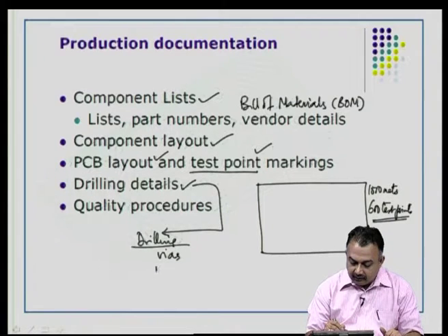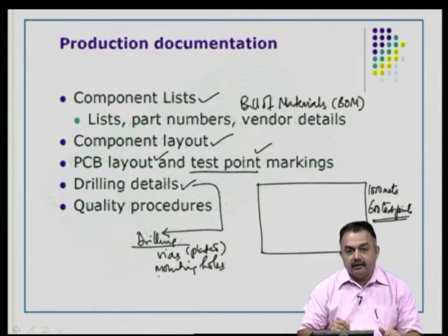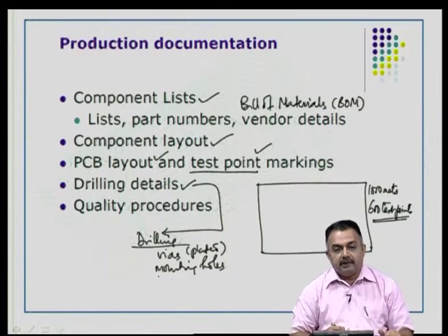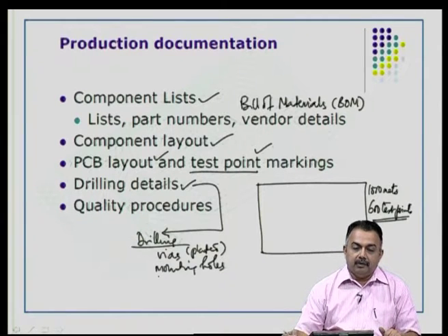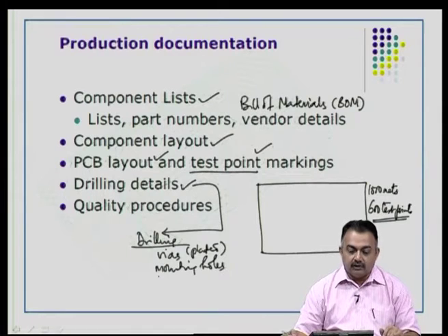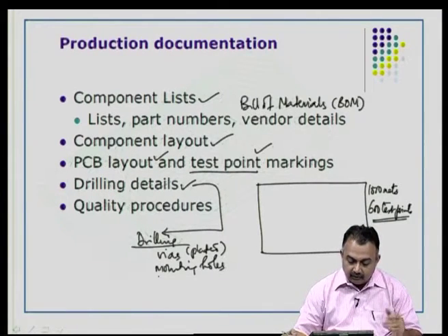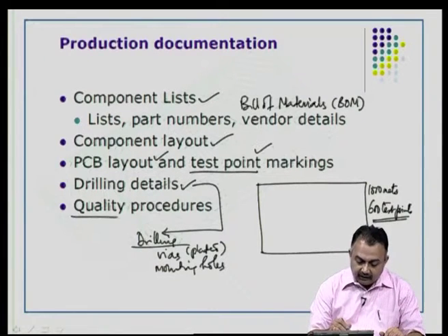Some are mounting holes, as I said, not necessarily to be plated, but these are plated to interconnect different layers, and in some cases there may be special cutouts that may be required for physically mounting your board onto the chassis of a product. All of these are done in the drilling process, and those details need to be documented, and the quality test procedures have to be followed.